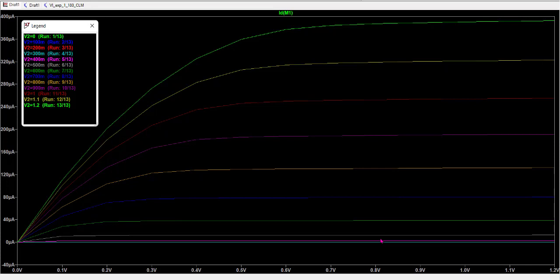Because MOSFET is a normally off device, right? Enhancement MOSFET we are seeing. As we give the positive voltage in an NMOS, the current will keep on increasing, because then the inversion layer will form. If you remember, we had studied that as we keep on reverse biasing the gate, the inversion layer keeps on increasing, and that inversion layer makes sure there is a channel formed there, right?